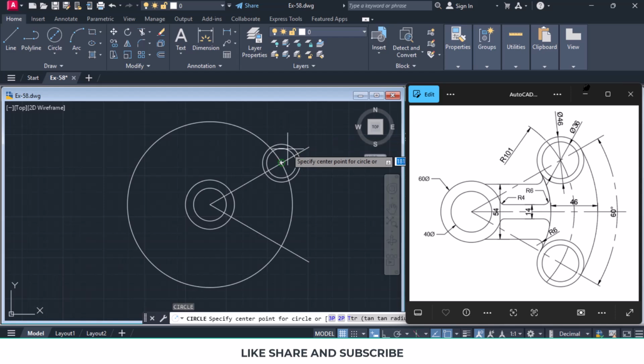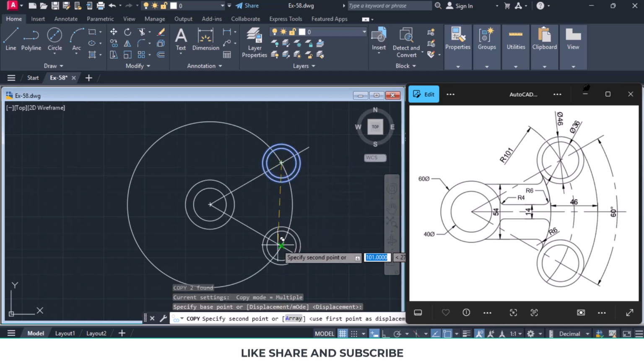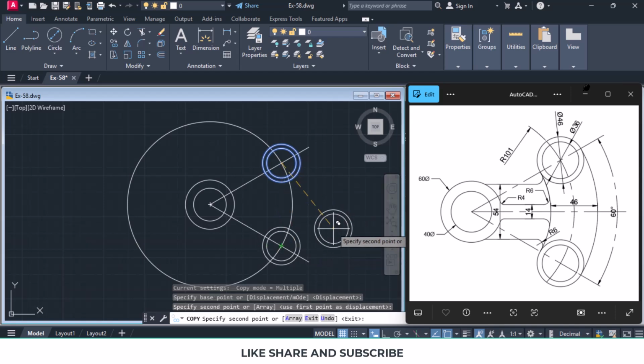Now these two circles are there. We'll copy them over here. So we press escape to come out of the circle command. We select this circle, CO for copy. We specify this as the base point and click at the new point of displacement. Press escape to come out of the copy command.